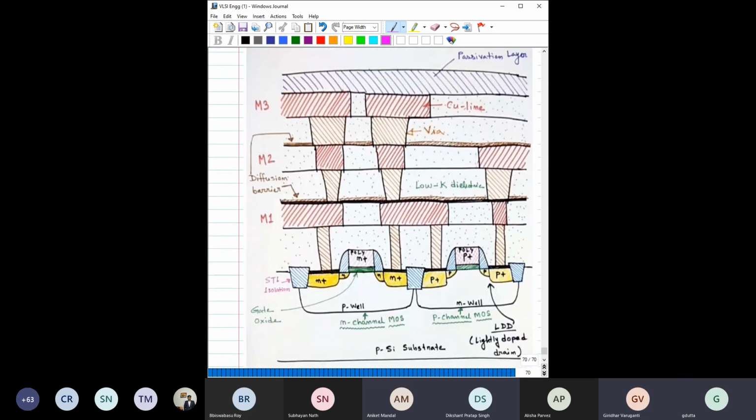To end up, we have seen a couple of techniques. MOSFET fabrication has been explicitly discussed. CMOS process flow has been explicitly discussed. Now this image would give you a final view on this. So this is the NMOS channel, and you can see this is the P substrate. We have made the P channel, we have made the N channel, and here we have created this N plus, and this N. So this is basically the LDD structure, like that.